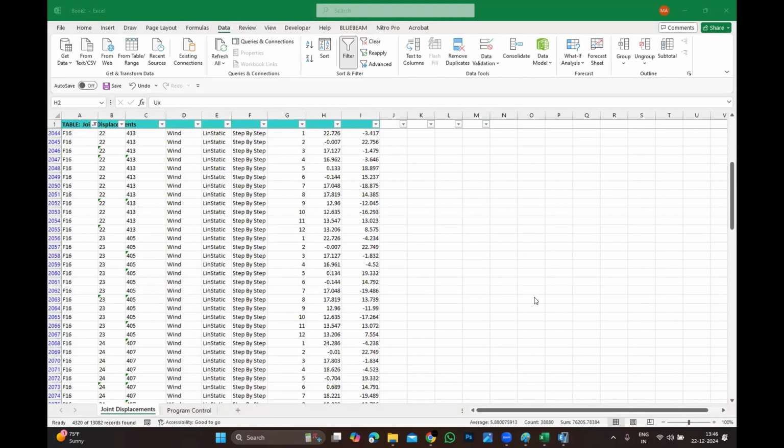Proof what you will do? If there is no beam, you can add beams, or you can increase the beam by another 100 millimeters, 200 millimeters, because you are getting more rigidity. Once you have controlled over there, that's it. You don't need to control right below.